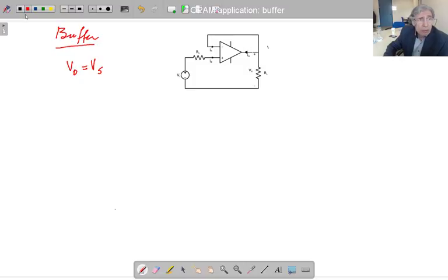So immediately you are going to say that if this is equal, you've got to connect a short circuit here, this becomes equal. Why do you need all these elements? Let me finish it and then answer that question. Well, definitely we need the definition relation of this ideal operational amplifier. Just to remind you, Vp minus Vn is almost 0, and Ip equals In, which is almost 0.